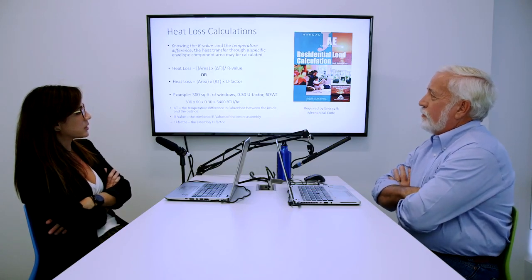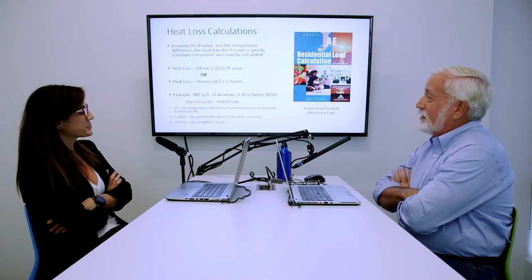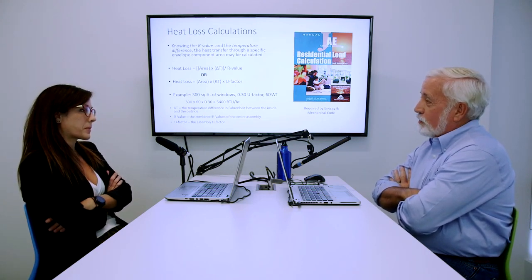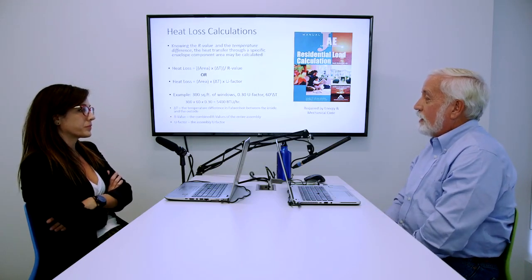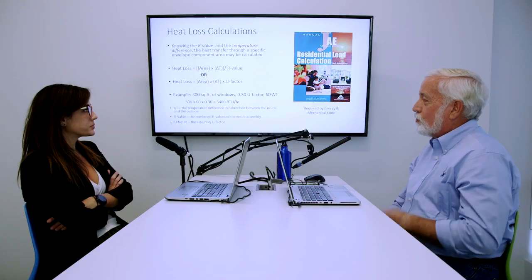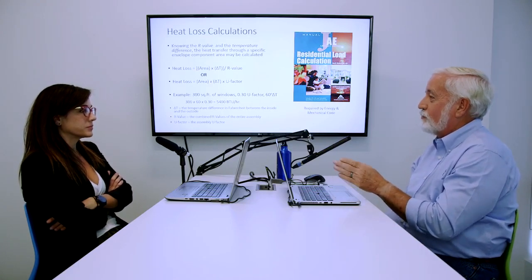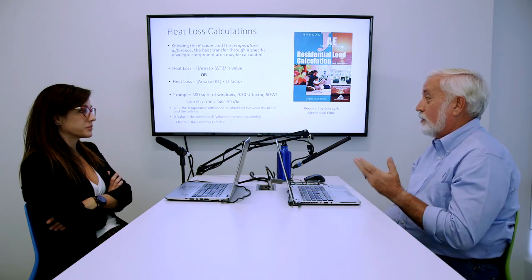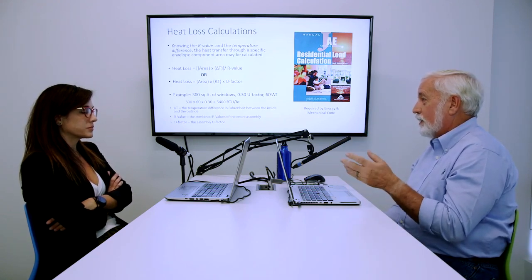8 years ago, when we really started getting active on energy code, and 8 to 10 years ago when we really started pushing it, the prescriptive table code requirement was 0.35. And some manufacturers struggled. 0.35, 0.34, 0.36, 0.37 was where a double pane vinyl window with low E coating on the glass ended up.